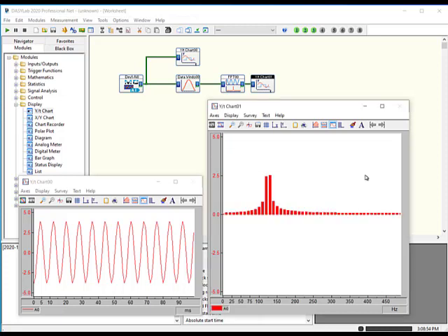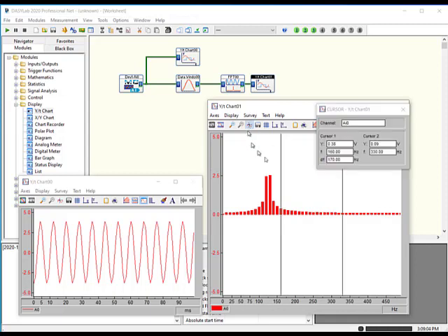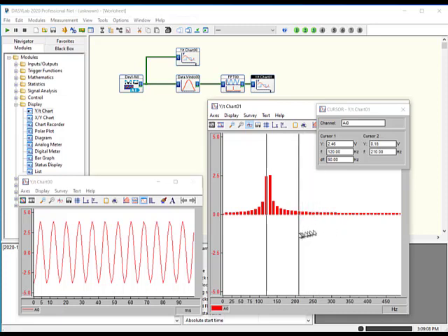It is the same function. It is a function that shows you the individual frequency lines. And again, if I turn the cursors on, you're going to see very clearly that my cursors are on adjacent bars 10 hertz apart.